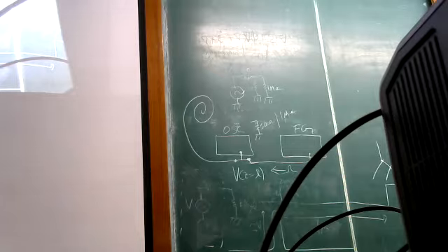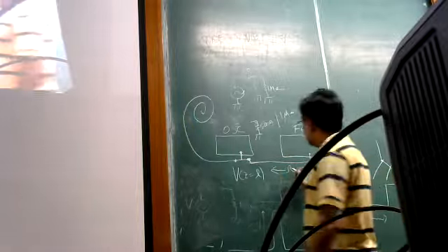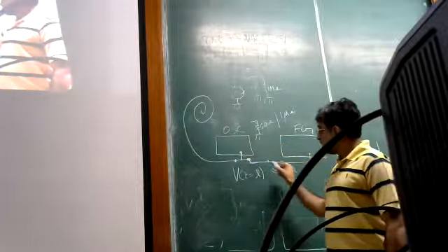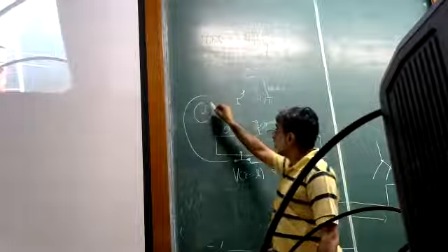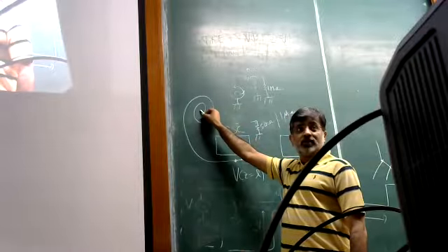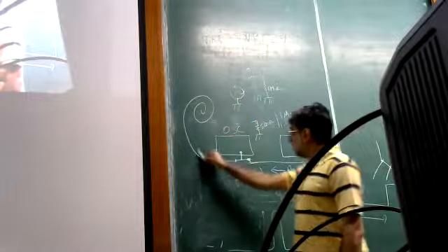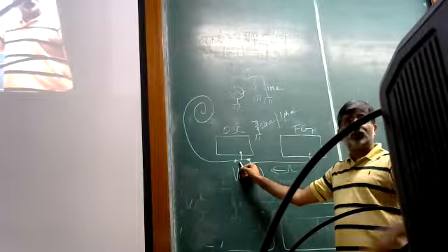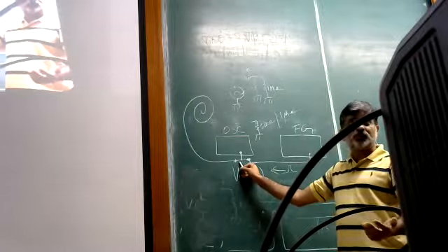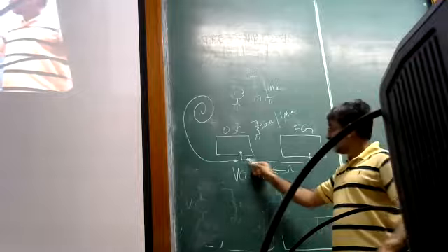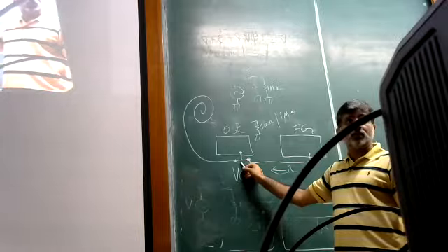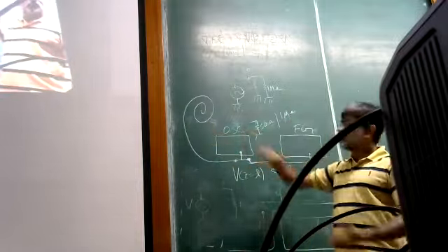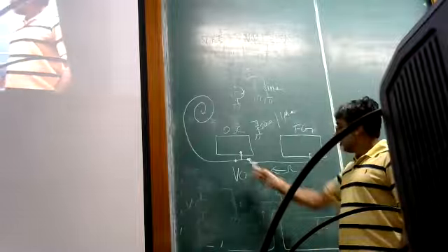Which cable? This extra cable, right? So this pulse, because this tap is not going to do anything to it, just propagates along here all the way to this end. Open end reflects, comes back, and will reach the oscilloscope again. So the oscilloscope will show another pulse, which is time delayed from the same pulse which arrived a little while ago. And the round trip time will be twice the time to go from 1 to n, right? Because it has to travel twice. And then what happens?